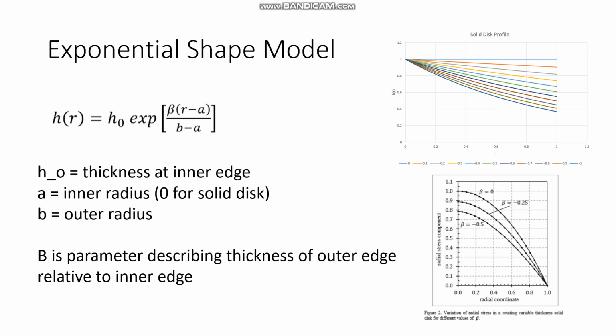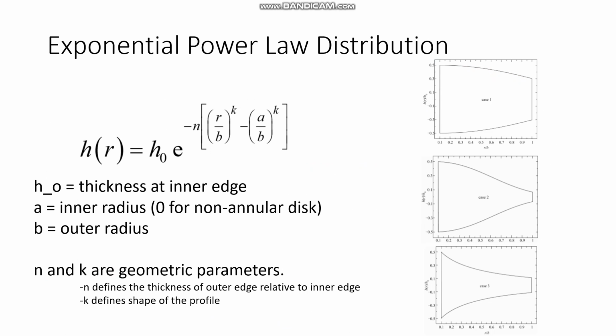So I'll be looking at these various shape functions and keeping other parameters constant, potentially normalizing for mass of the system, looking at how the maximum von Mises stress is affected, because it's likely that that value is what's going to be driving the design if performing something like an LCF analysis.